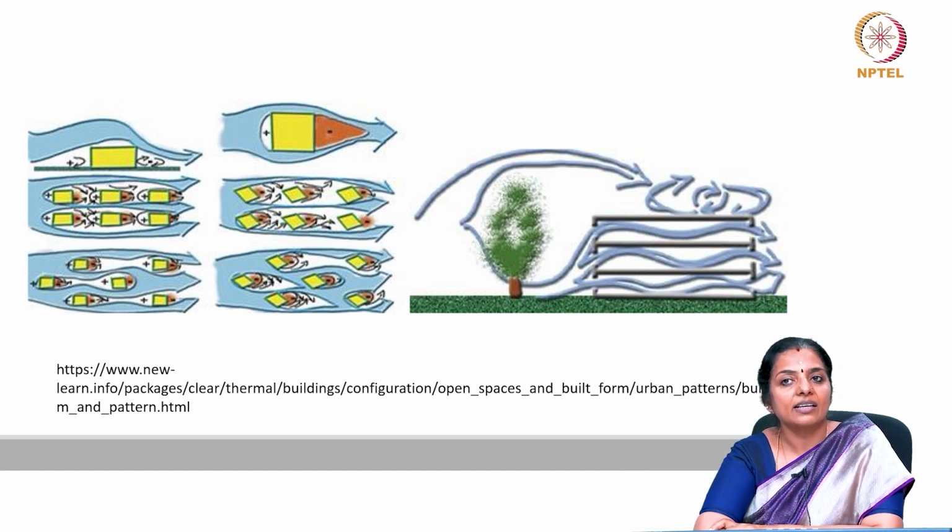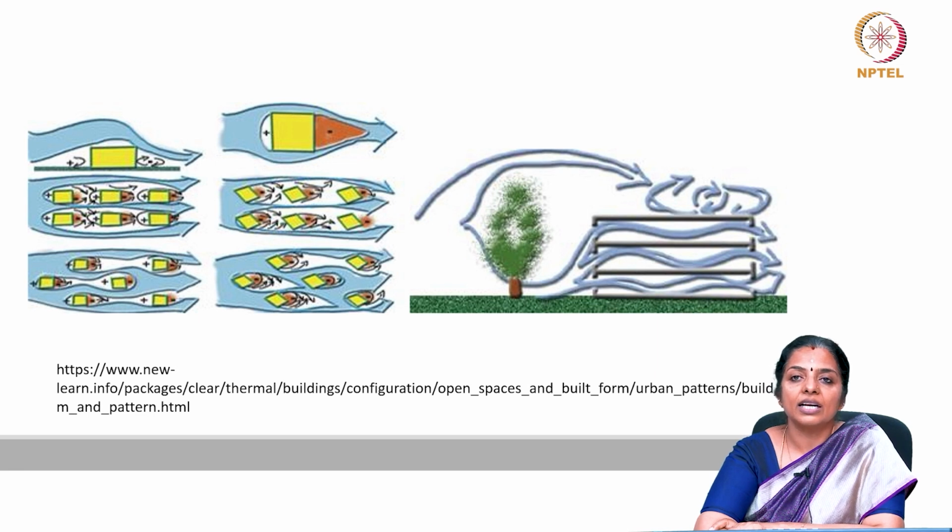In this case, the interior of the buildings suffers from poor ventilation while the adjacent open spaces experience high wind velocities. Orienting buildings at an angle in relation to the wind direction can produce relatively homogeneous wind patterns around them, thus creating better ventilation regardless of the relative position of buildings within the built-up arrangement.